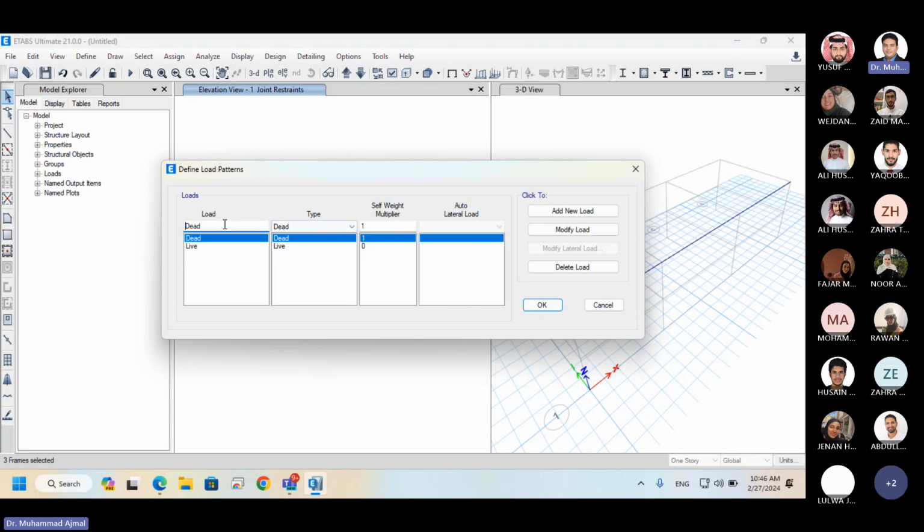Now I will add a new load pattern, because I want to apply 21.68 myself, from my side. Those loads include self weight, superimposed load, and the weight of the slab. So I will call it DL, a new name, which includes all types of load from our problem.